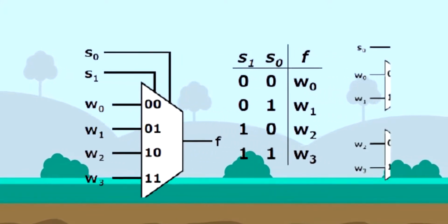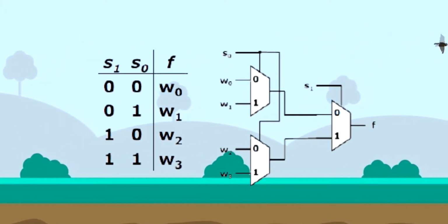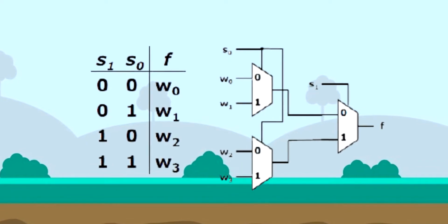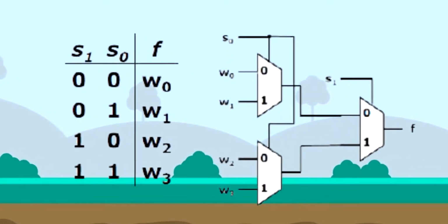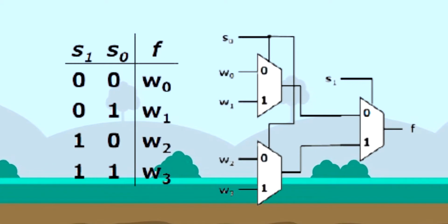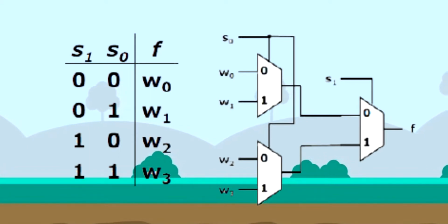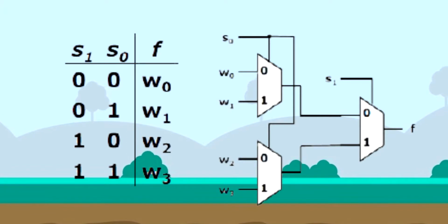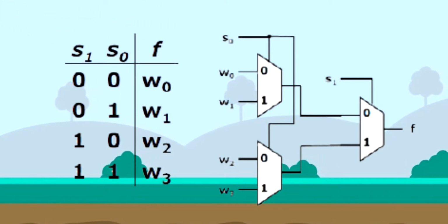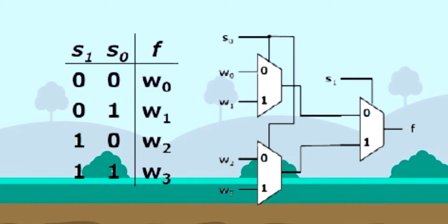The 4-input multiplexer can be constructed using 3 MUX with 2 inputs. As each multiplexer has 2 inputs, we just need 1 selector for each multiplexer. Now, we will discuss how a multiplexer works. As we can see in the diagram, if the value of the first selector is 0, the inputs chosen are x0 and x2. On the other side, if the value of the first selector is 1, the inputs chosen are x1 and x3. Now, how about the second selector? You can determine it by yourself, right? Yes, it depends on the first line output, which becomes the input of the multiplexer with selector 1, and it has the same pattern.